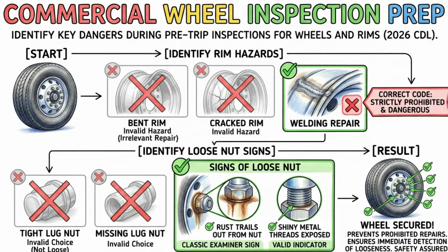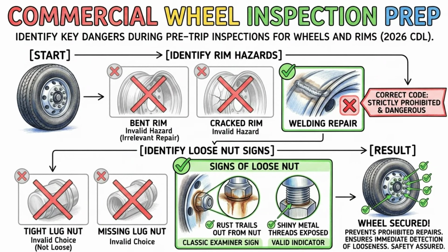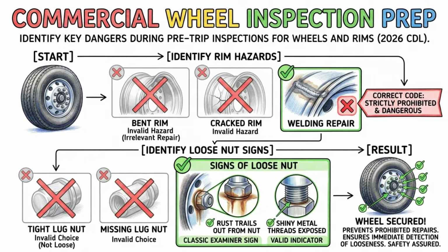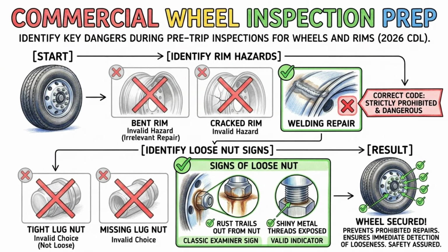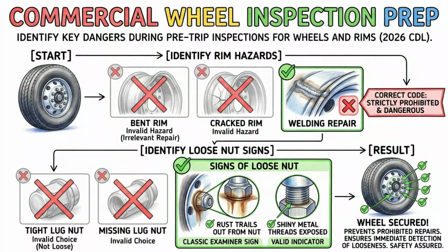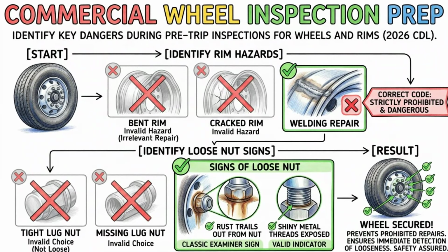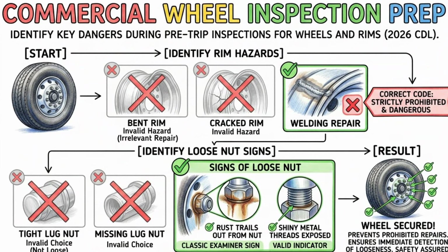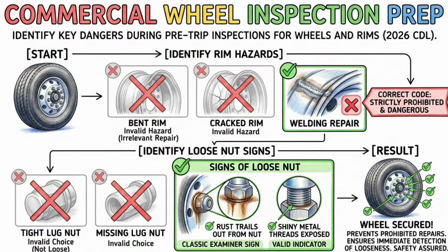Finally, the general knowledge section covers basic adjustments for poor driving conditions. When the road is wet, your braking distance increases significantly, so you must reduce your speed by about 1/3. If you are driving on packed snow, you should reduce your speed by at least half. When the road surface becomes icy, you must reduce your speed to a crawl and stop driving as soon as you can safely do so. Knowing these exact speed reduction fractions for wet, snowy, and icy roads is essential for passing the written exam.